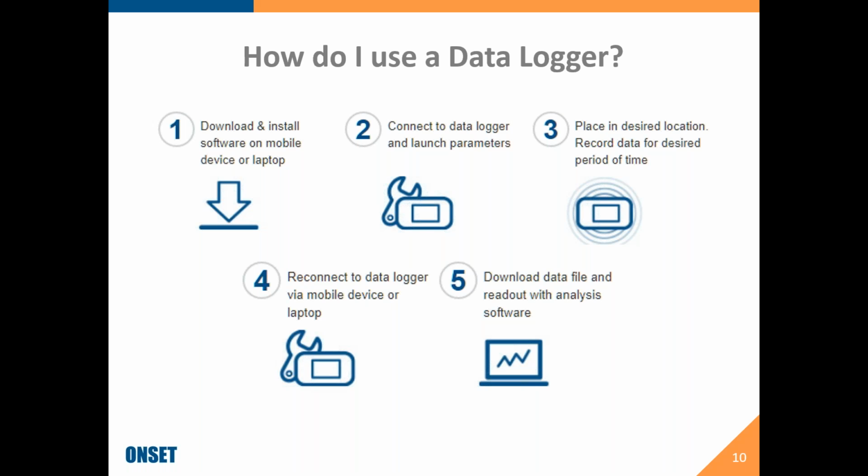The fourth item there for you to read out that data logger is you're either connecting it to the computer or you're going to open up the app on your phone and be within range of it and open up that software where you again have control. You'll be prompted to read it out and save that data file. Now, there are different kinds of data files.